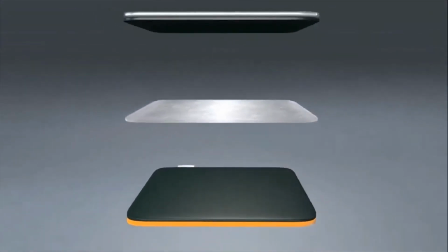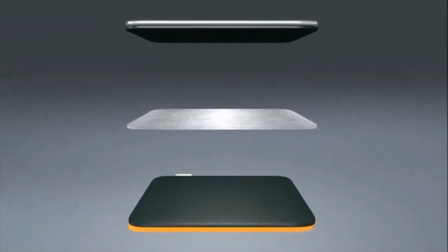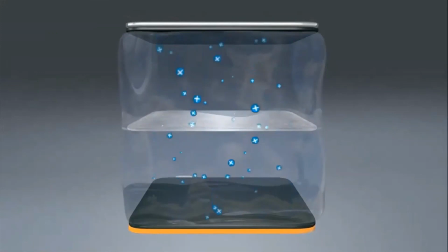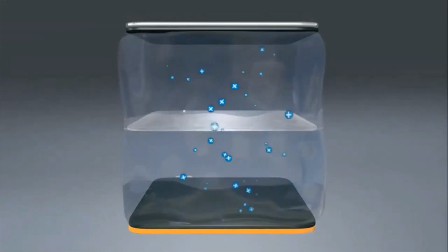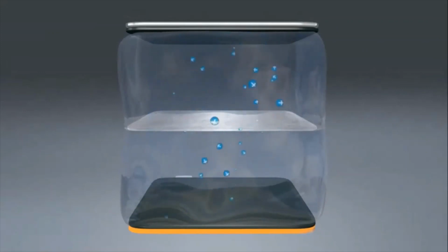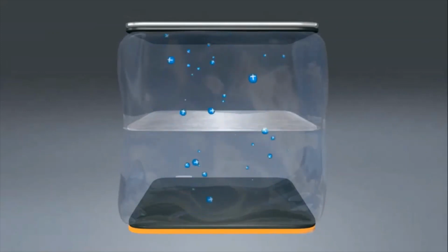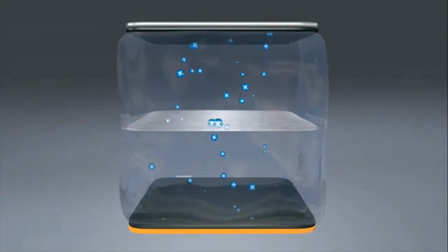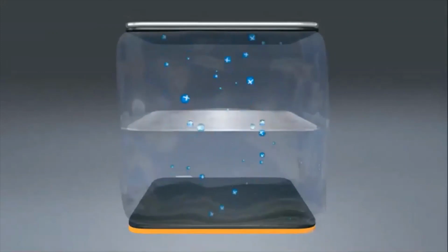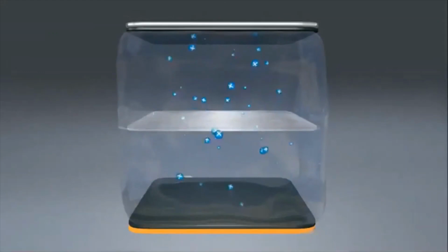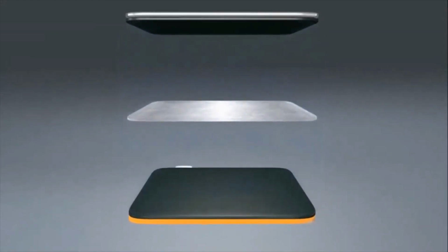Let's take a look at what happens when a battery is charged. The positively charged lithium ions pass from the cathode through the separator into the layered graphite structure of the anode, where they are stored. Now the battery is charged. When the battery discharges, that is when energy is removed from the cell that can be used as electrical energy outside the battery, the lithium ions travel via the electrolyte from the anode through the separator back to the cathode. The electric motor converts this electrical energy into mechanical energy, making the car go.